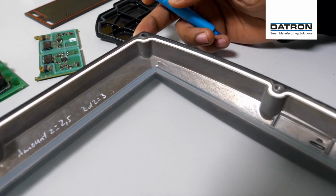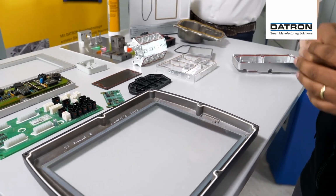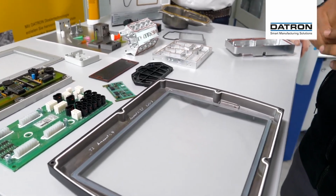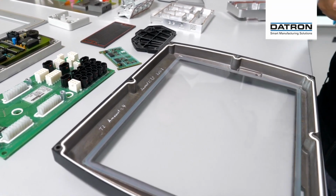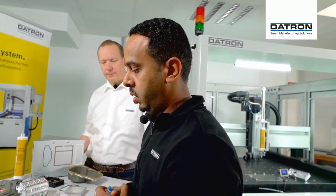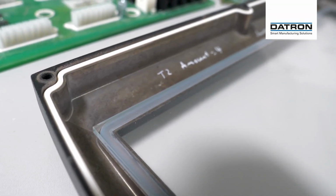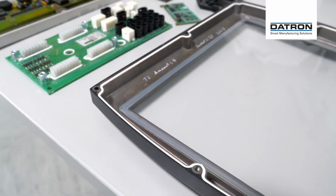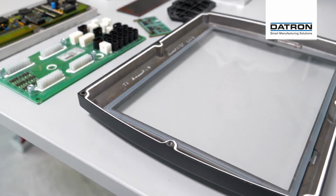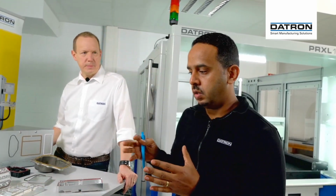The application itself is that we need to place the aluminum frame into the machine, start the program and dispense a material. This can be a silicone or silicone-free material, a glue. Afterwards we join the glass plate or the display, touch screen, etc. to the aluminum frame and material, and this will cure directly on the part. So after we dispense and put both parts together, this needs to be placed somewhere to cure the product.